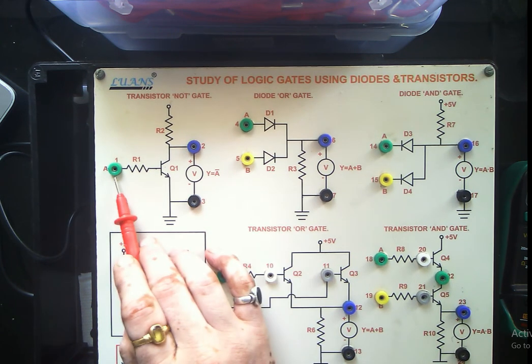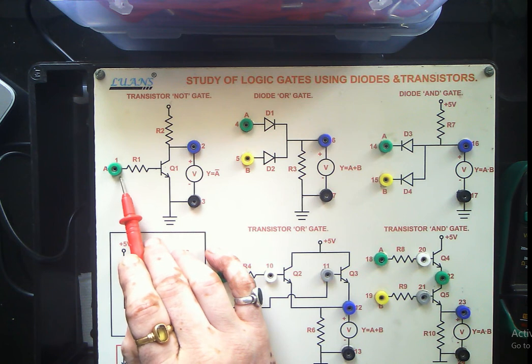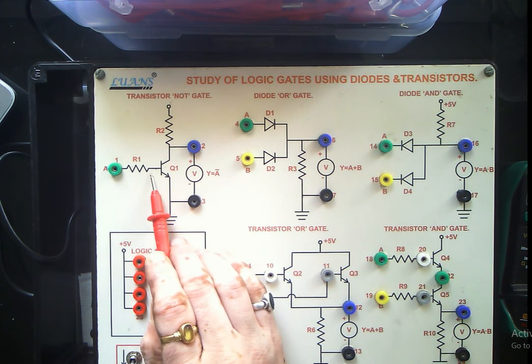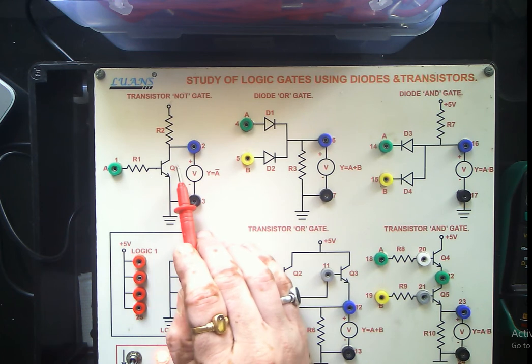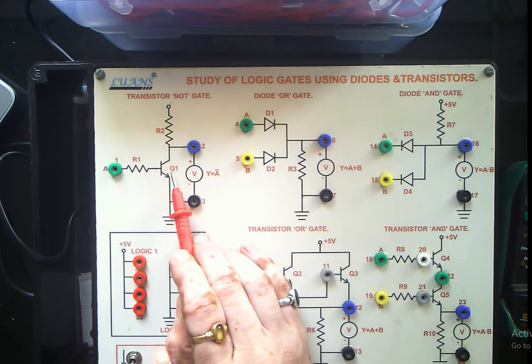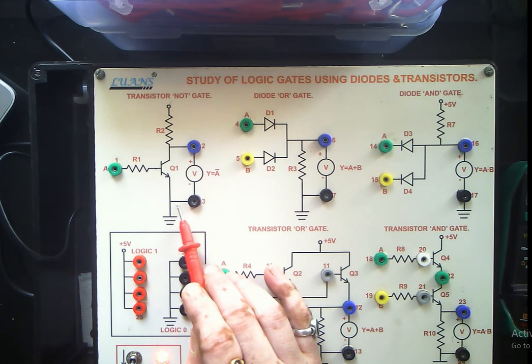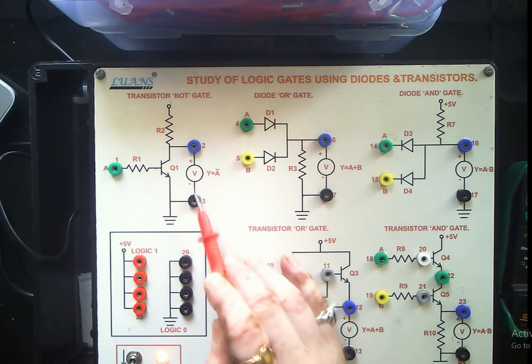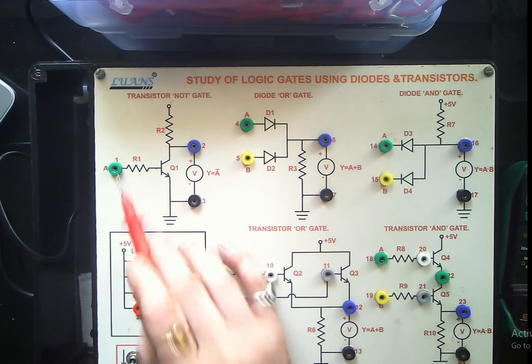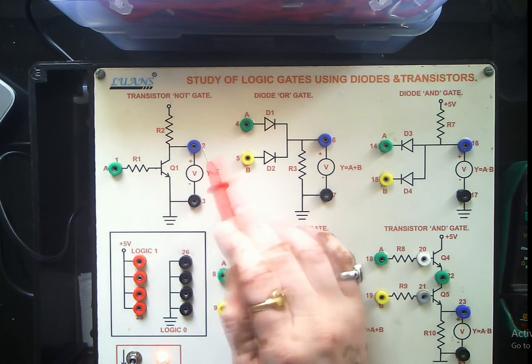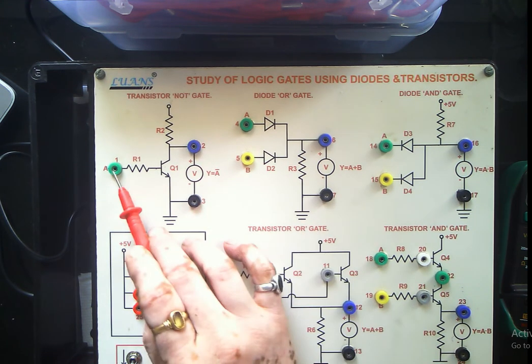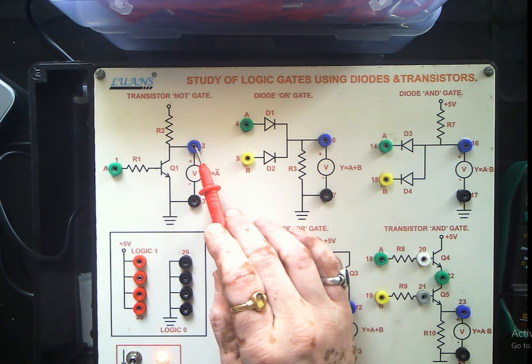Now suppose we have made this terminal low. In such a condition, there will be no current to the base and definitely the transistor will not be conducting. So when the transistor is in a non-conducting state, the entire voltage will be developed across the collector and emitter. Therefore, we are finding such a result. Whenever we apply a high signal to the base, the output is low. When we apply a low signal to the base, the output is high.